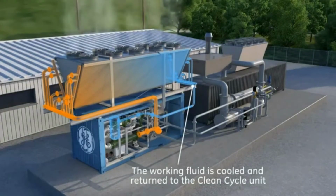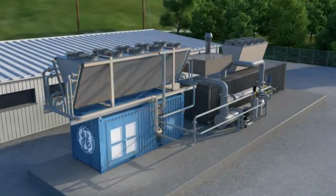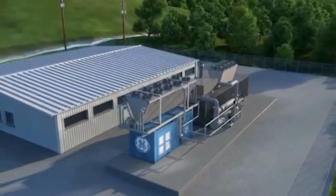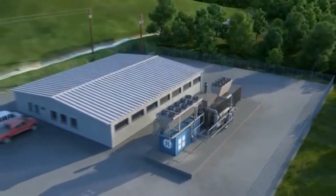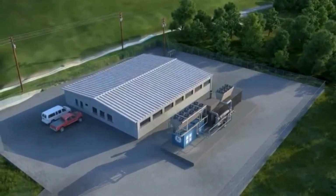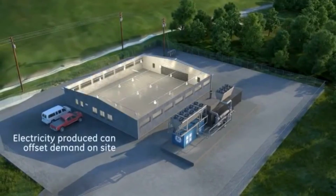In the condenser, there is heat transfer from the working fluid to the cooling water flowing in a separate stream. The working fluid condenses and the temperature of the cooling water increases. Mass and energy rate balance for a control volume enclosing the condensing side of the heat exchanger give Q out per m equal to h2 minus h3.